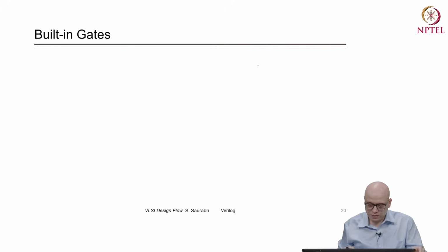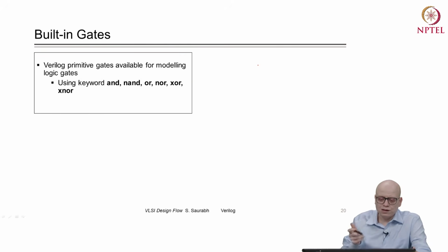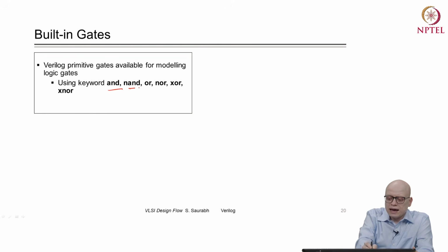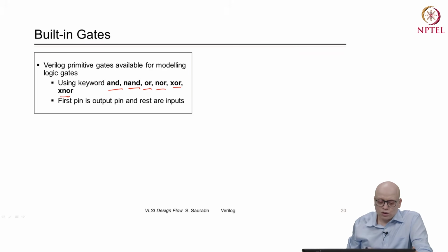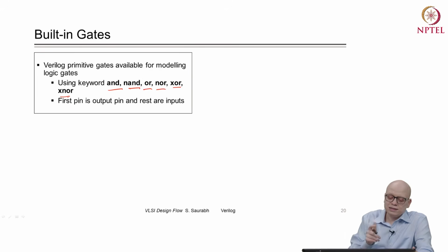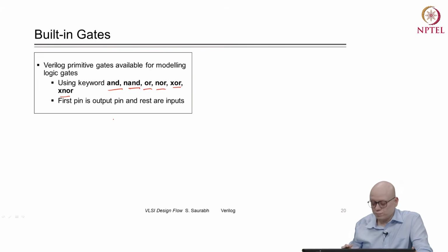Now, Verilog also supports built-in gates. For example, there are keywords and, NAND, OR, NOR, XOR, XNOR, which we can use directly in our code for making logical connections and making circuits. The convention here is that the first pin is the output pin and the rest are inputs.